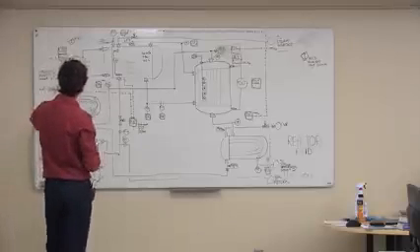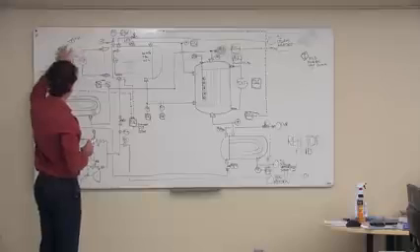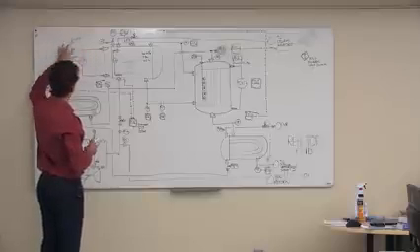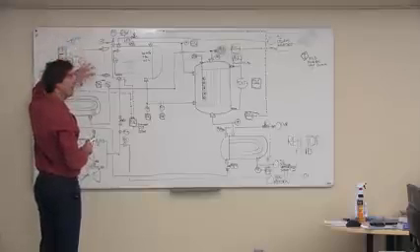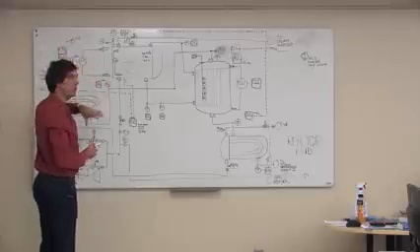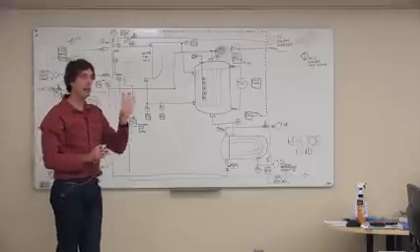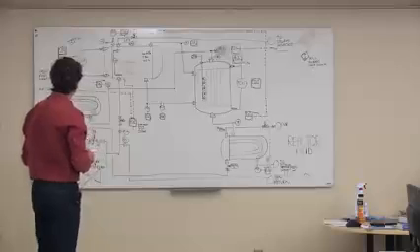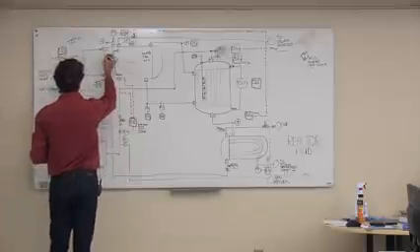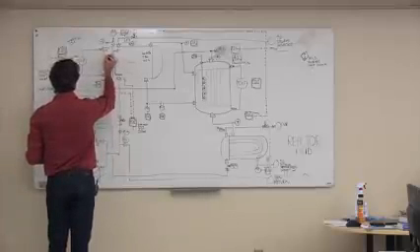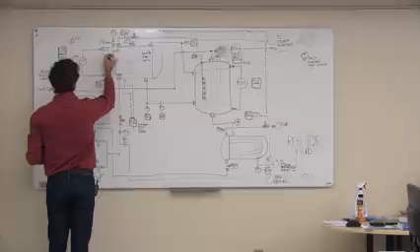The only thing that's sort of unsatisfactory about this is the fact that you're trusting the level transmitter. So if the level transmitter fails for any reason, then you're in trouble. So you might be smart to do one of two things.